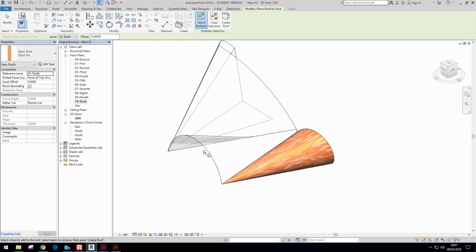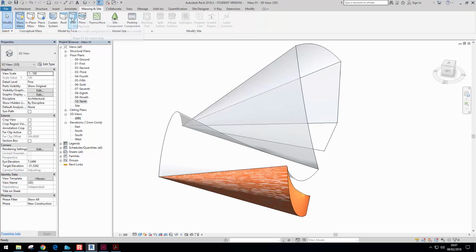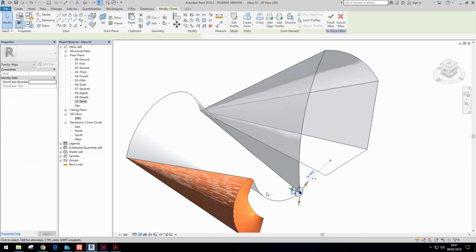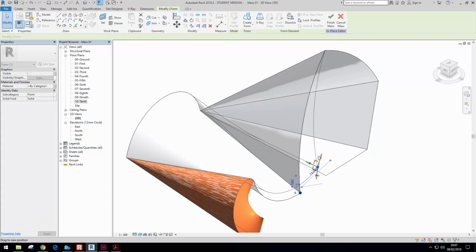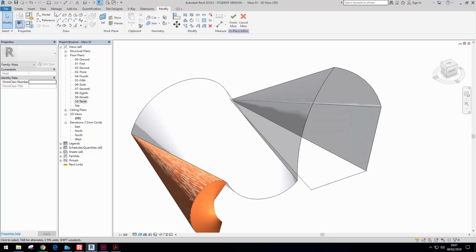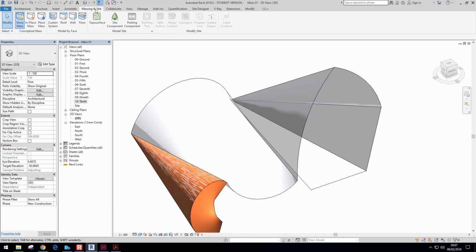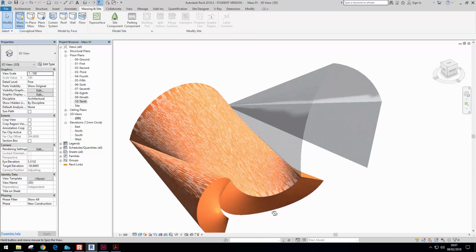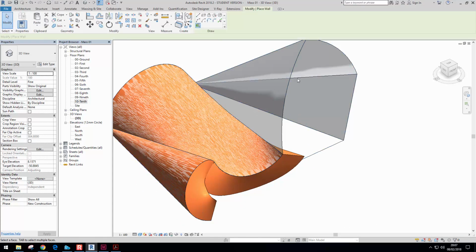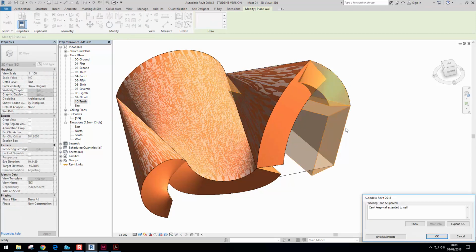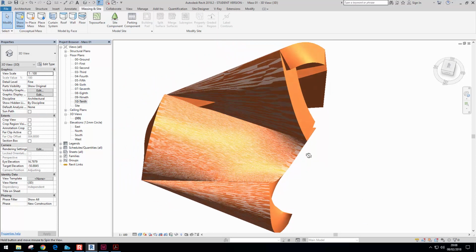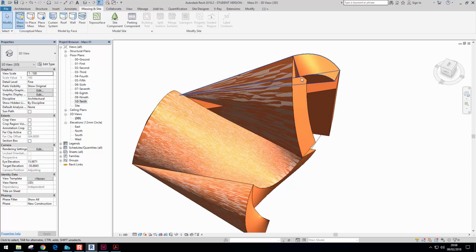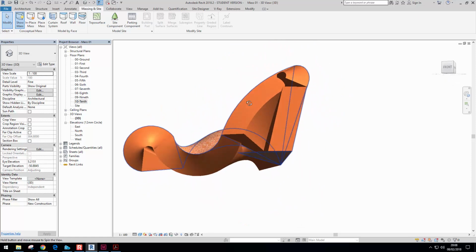So click roof. Oops, sorry. If I click wall, so you might have to go back and change that form so it's a bit more of a curve or not at a tight angle. So it might take a little while just to get the right angles. Okay, and again wall. Because it's doing it at a right angle, and that's showing the thickness of the material, you might get some overlapping similar to that, but you can amend it afterwards once it's modelled, or cut it away.